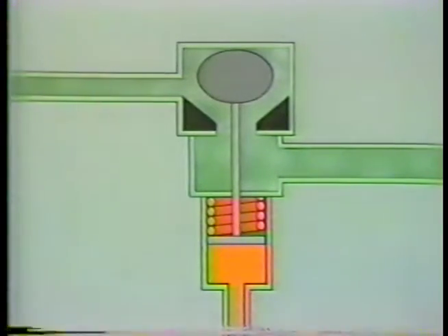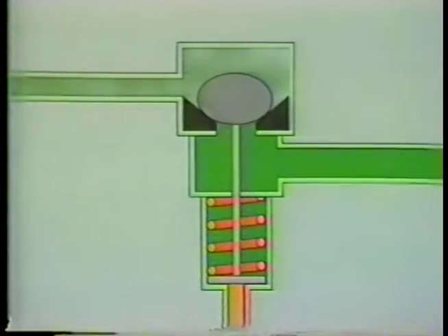It's opened and held open by hydraulic oil pressure on the piston. The piston compresses the spring and pushes the valve stem. The stem lifts the valve disc off its seat. In this position, steam flows toward the high-pressure turbine. When the turbine is tripped, the hydraulic oil is quickly bled from underneath the piston. As this happens, the spring expands, forcing the valve disc back on its seat.